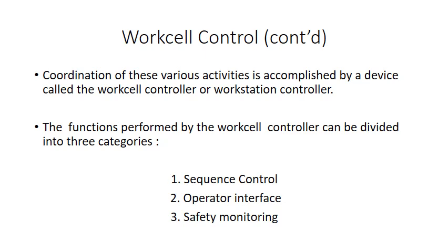Coordination of these various activities is accomplished by a device called the workcell controller or workstation controller. The functions performed by the workcell controller can be divided into three categories: sequence control, operator interface, and safety monitoring.